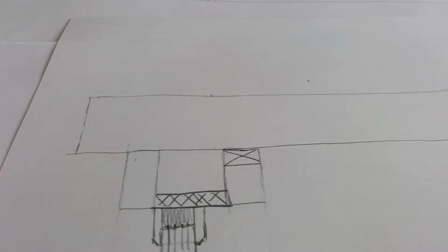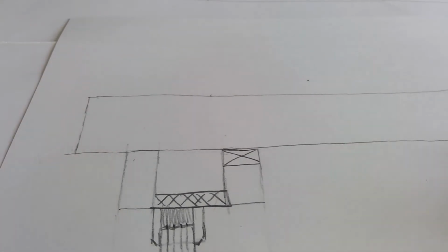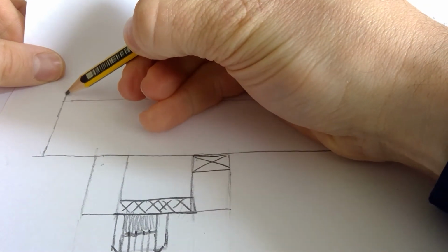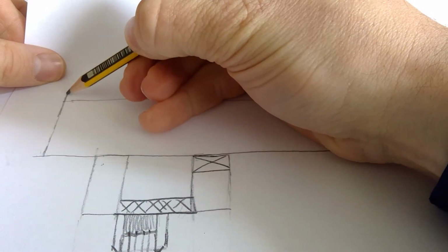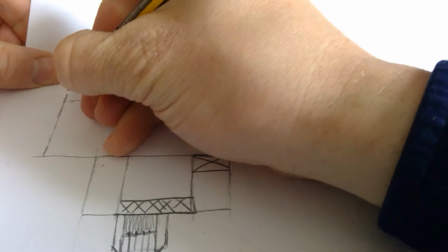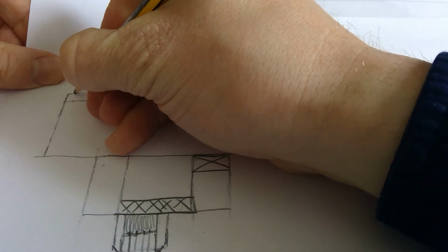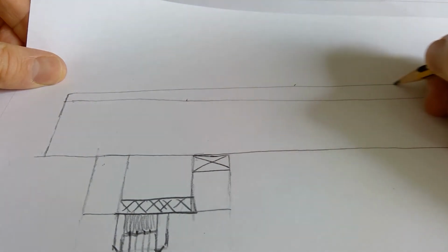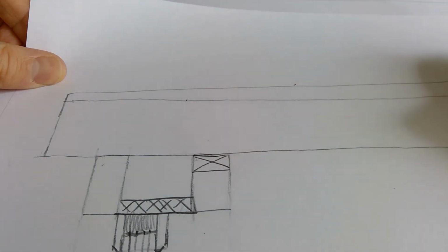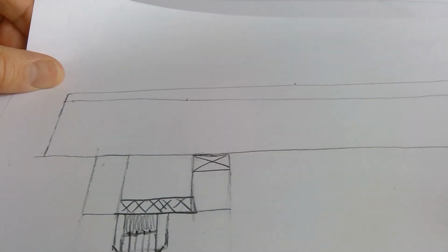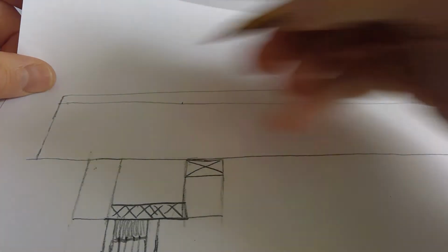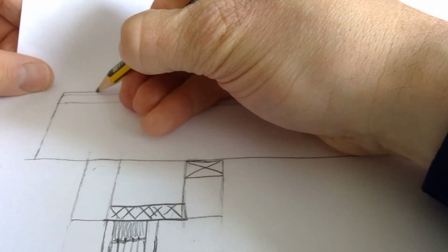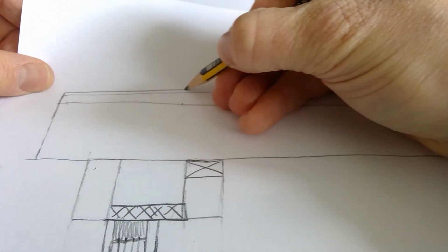So on top of the joist, next we're going to draw our fairing piece. Again, the fairing piece size can vary, so go up there maybe around 10 millimeters and project off at an angle. Set up your set square at the slightest angle, around maybe 10 degrees or less than 10 degrees even, and go off at a little angle there for your fairing piece. On top of the fairing piece, we have a sheet of plywood or OSB, which just covers all that up.